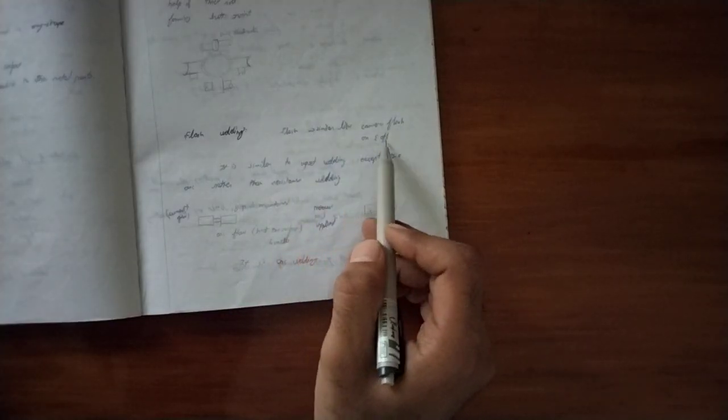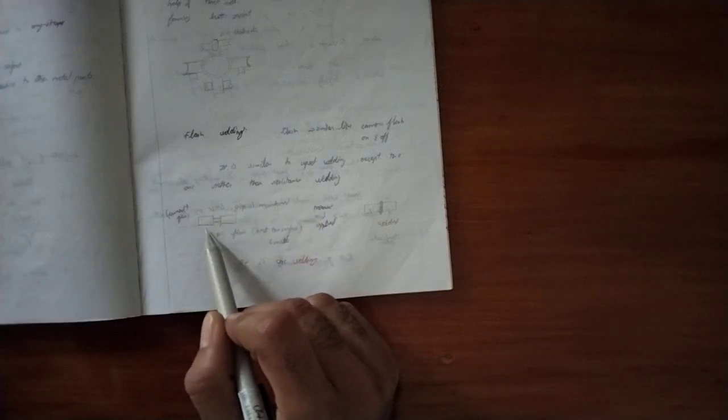So next one is flash welding. Flash is similar to a camera flash, on and off. It is similar to upset welding except it uses an arc rather than resistance welding. You can see the gap is made and the heat is produced, meaning the current is passed between the two sides, and later we apply pressure and weld. It is similar to arc welding. You can see one side fixed and the other moves like this.